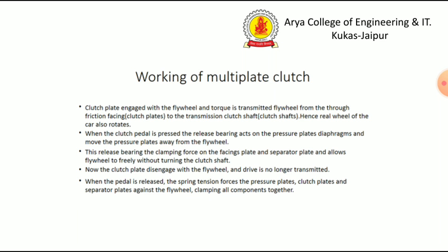When the clutch pedal is pressed, the release bearing acts on the pressure plate's diaphragm and moves the pressure plates away from the flywheel. This release bearing removes the clamping force on the facing plate and separator plates and allows the flywheel to spin free without turning the clutch shaft. Now the clutch plate disengages from the flywheel and the drive is no longer transmitted.